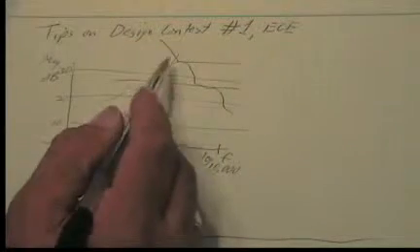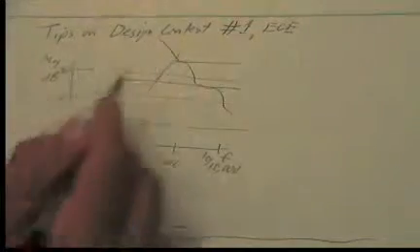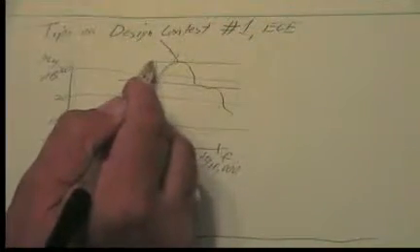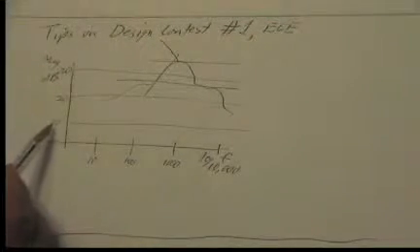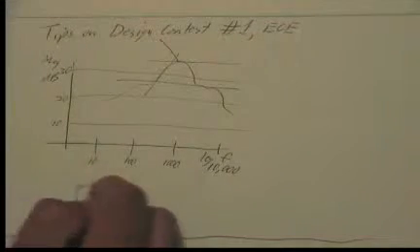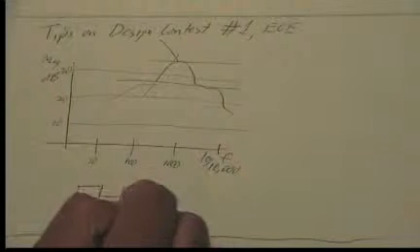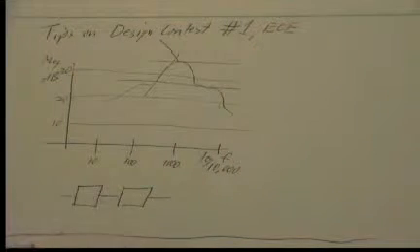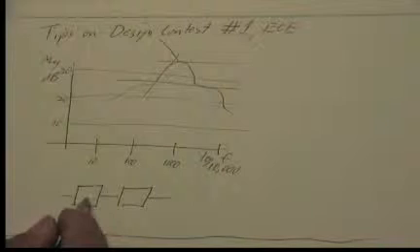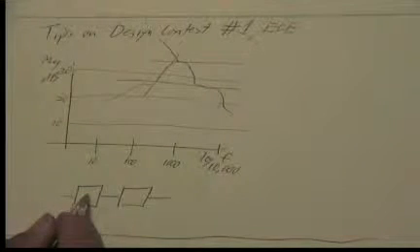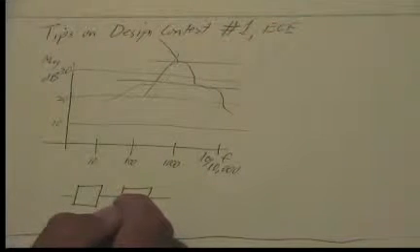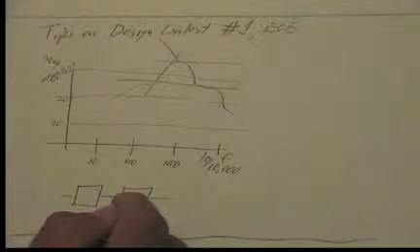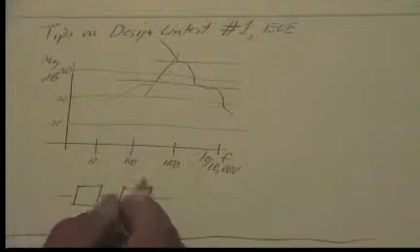This, which is the original signal, times this signal, is going to produce a flat signal over that range, because in dB, when you cascade two filters like that, the gain at any particular frequency in this one, in dB, gets added to the gain at that same frequency of this one to produce the overall result.